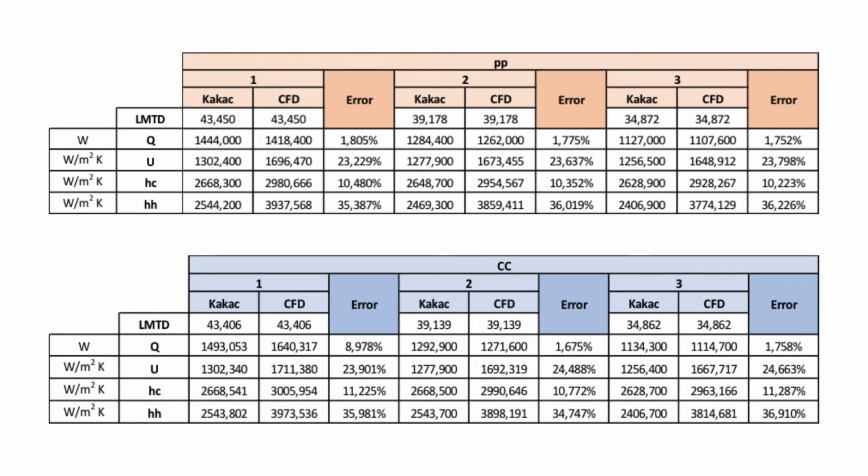The energy balance is carried out and it is observed that, although it does not completely converge, the difference is not too noticeable, and that it may have to do with the fact that we're assuming that we will not have losses anywhere and that no heat is being consumed transferring through the shell. The use of the value F was considered so that it corrects the balance. However, it was not found because the value of F must be less than 1 and no value less than 1 could close our balance.